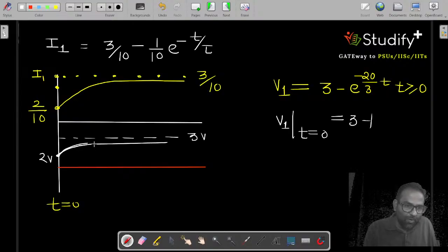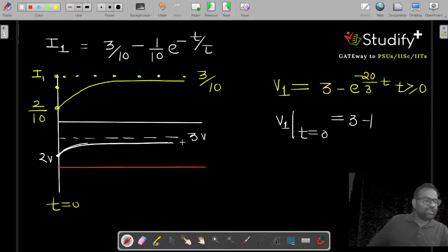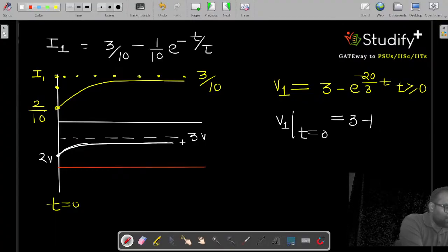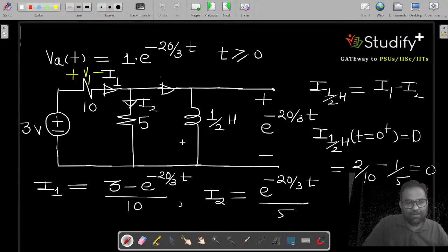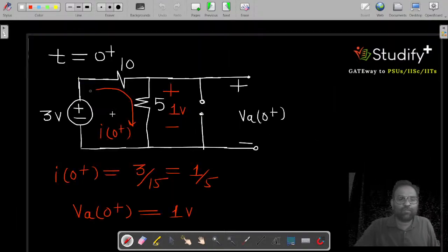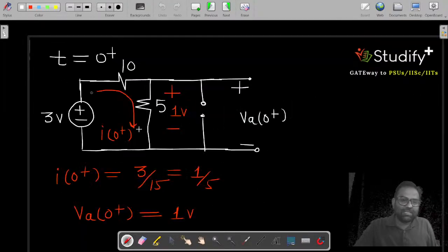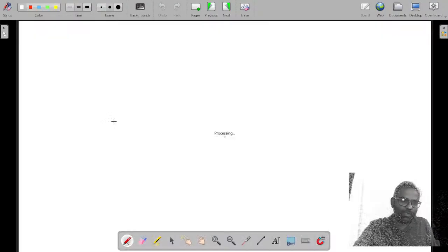These are the waveforms for the current across the resistance. And what is next? Next we are having one more component, and that component is I2. So what is I2? The potential across I2 is the same as the potential across the inductor, because both the components are connected in parallel. But what is the situation of current? I am calling this current I2. So if I draw the I2, what is the value of I2?